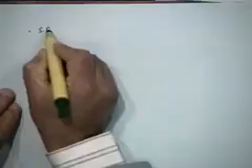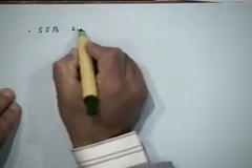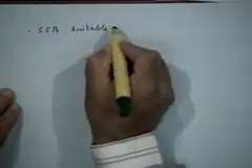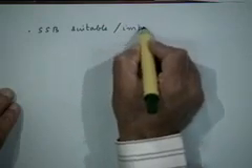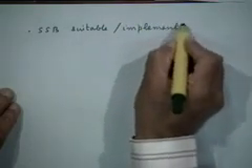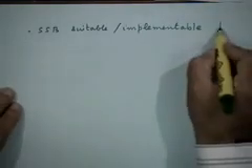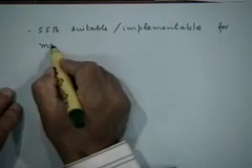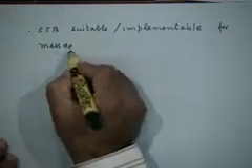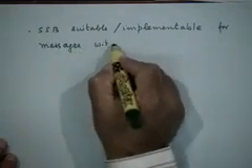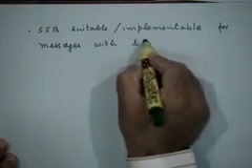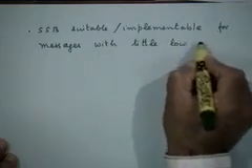So basically, let me summarize what I have said. What we have said is that SSB is suitable and implementable for what kind of messages? For those messages which have relatively less energy content at low frequencies, right? For messages with little low frequency content.